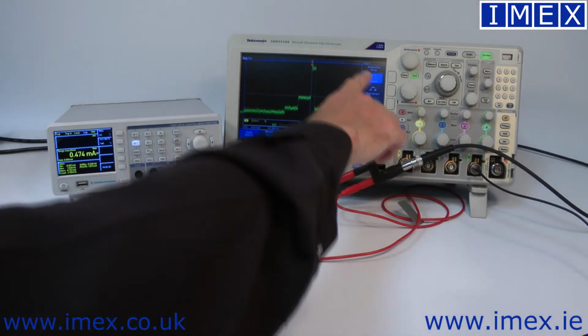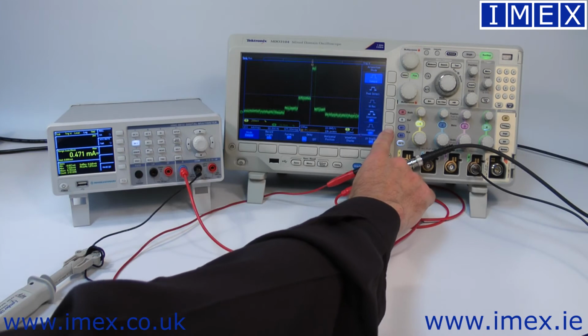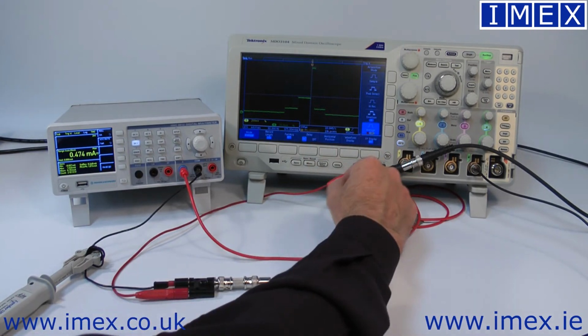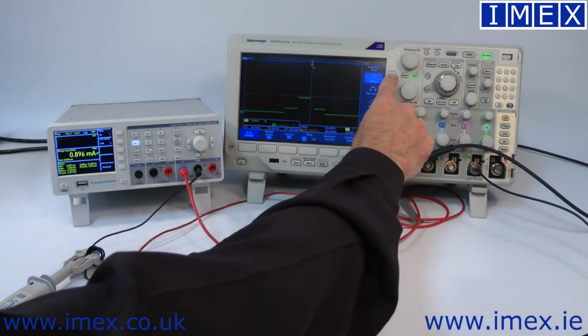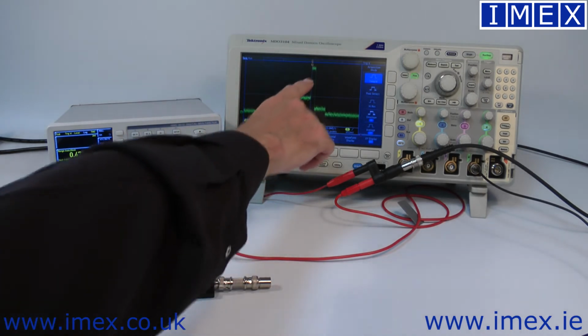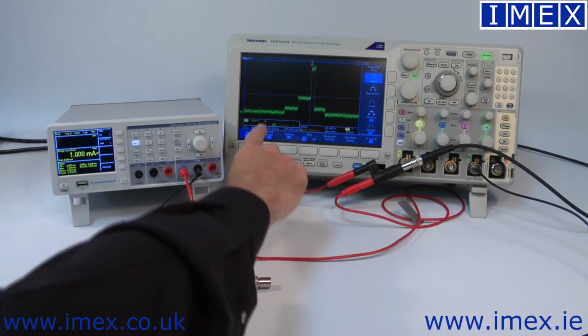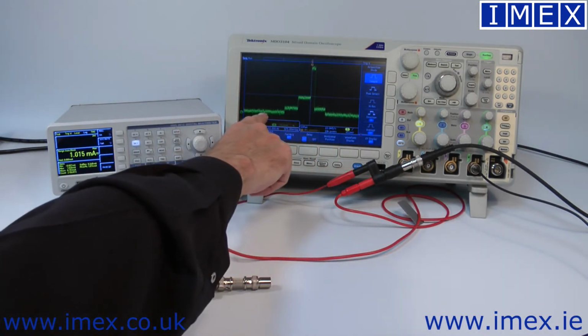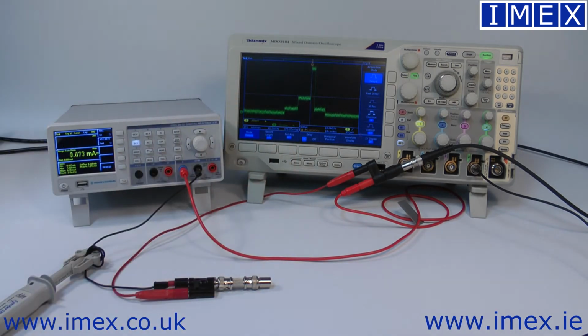We're still in sample mode, we're not averaging. I'll just prove it. I'll turn on the averaging. Obviously we've got a perfectly clean waveform, but we can't trust average because our signal may not be completely repetitive. So there we go, we can now measure our 20 milliamp peak, our low level kind of half a milliamp, background.